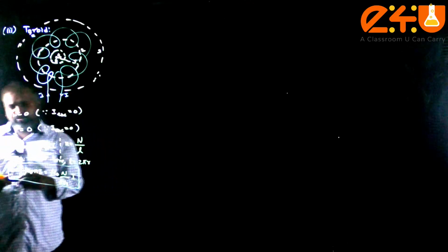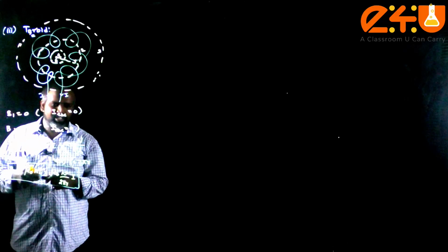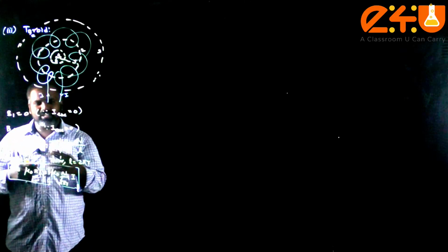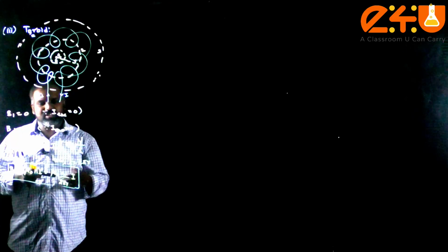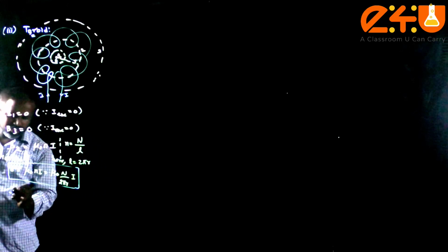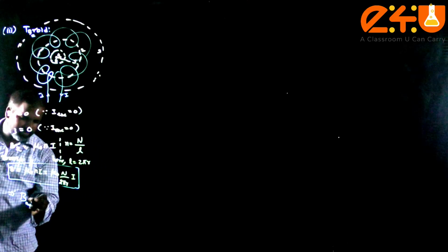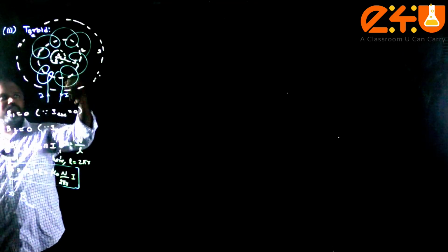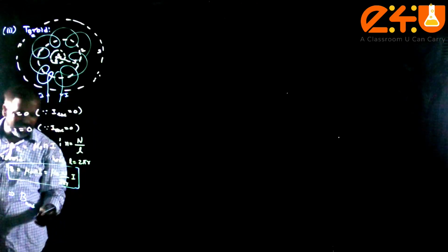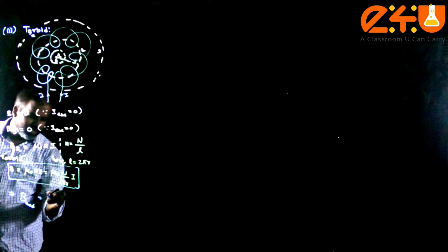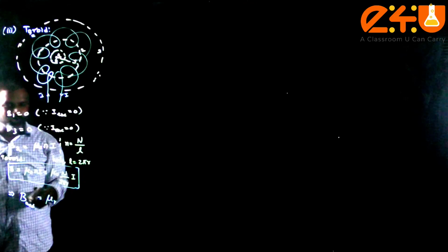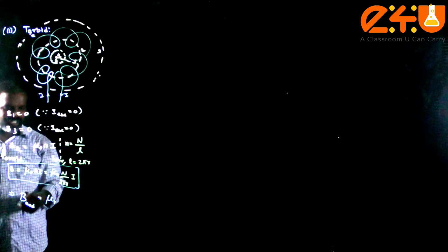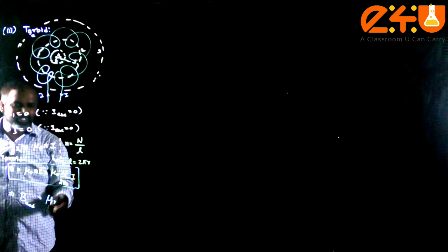As we discussed in capacitors, whenever a dielectric is inserted, the capacitance increases dielectric constant times. Similarly here also, if the hollow space is filled by any magnetic material, then B medium is equal to mu r times B. There we said epsilon r, relative permittivity, in a capacitor; here it is relative permeability.